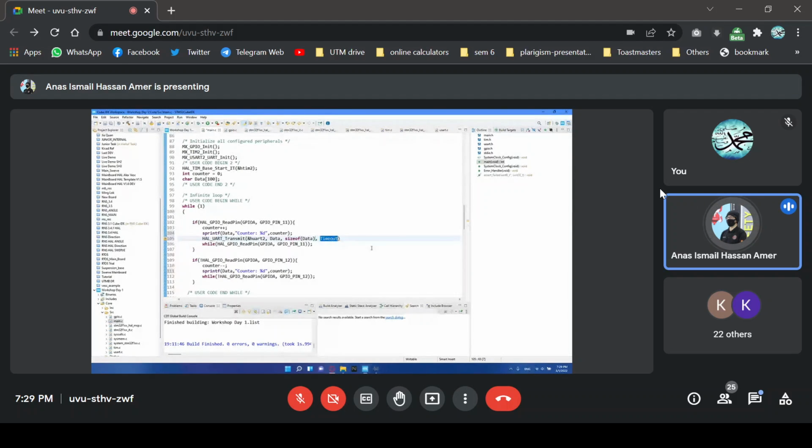And then we have timeout. Timeout is the time until it no longer attempts to send. So if your data is too long or something, then the timeout will cut it off. So let's set the timeout as like 50 or something. 50 milliseconds is a lot of time for data to be sent, since the microprocessor is at a 64 megahertz speed. So this should be enough.